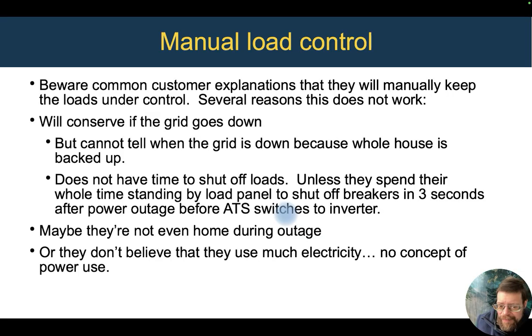Well, barely any power, say it's 1 kilowatt. That's 24 kilowatt hours a day. That's 1.5 batteries drained in a day. Get into a 4 or 5 day outage, that's quite a bit. So maybe barely any power is still too much for a reasonable sized battery bank.